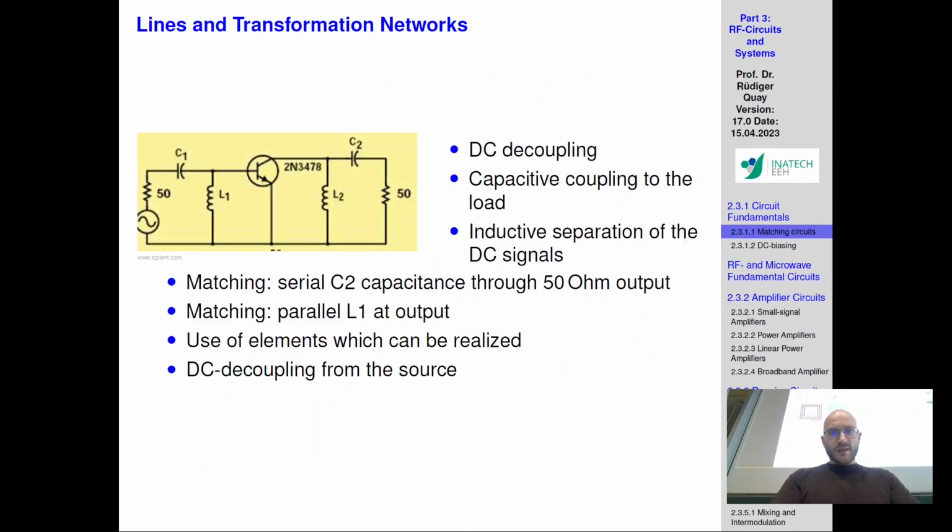Now, to go back to this topic: you have a transistor now. You have a model, and the model is this here in the middle. And now you're starting to design a transistor. You're designing this two-port network. A transistor, in this case, is a two-port network. You're adjusting your input matching, you're adjusting your output matching. An example of that was last lecture. I showed you ADS, how that looks in the schematic window. I showed you in CST how that looks in a 3D EM environment.